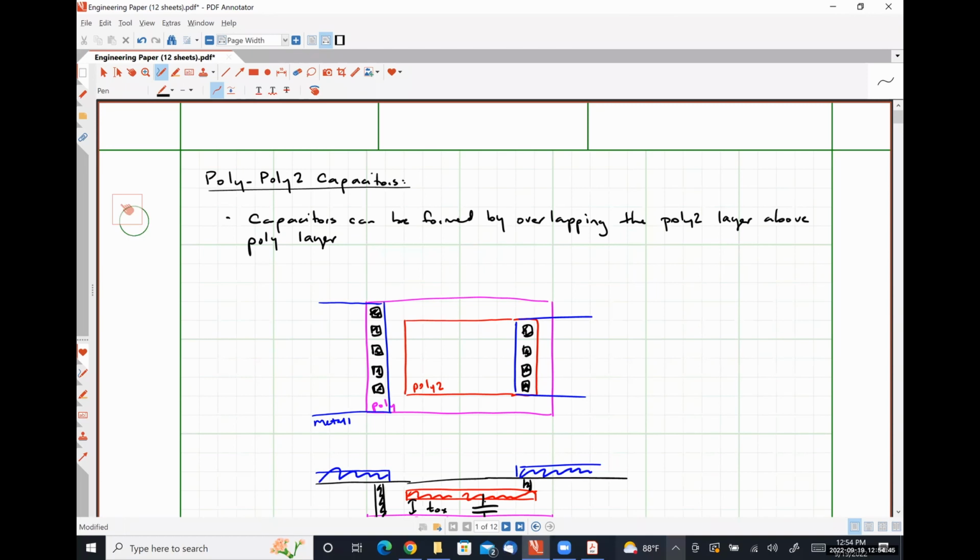An arguable added benefit of this is all of these are 10 ohm resistors effectively in parallel. So the more contacts I can put in, or the more vias that I can put in, the smaller contact resistance that I have. Because typically speaking, if we're connecting from one metal to another metal, and the metal has resistance on the order of 0.1 ohms per square or lower, and we'll talk about that in a little bit, throwing a 10 ohm resistor in the mix is just going to increase ohmic losses. Whereas if you can put a bunch of contacts in parallel, you're lowering the amount of losses that are going to occur as you send a signal from the top surface of the chip down or vice versa.